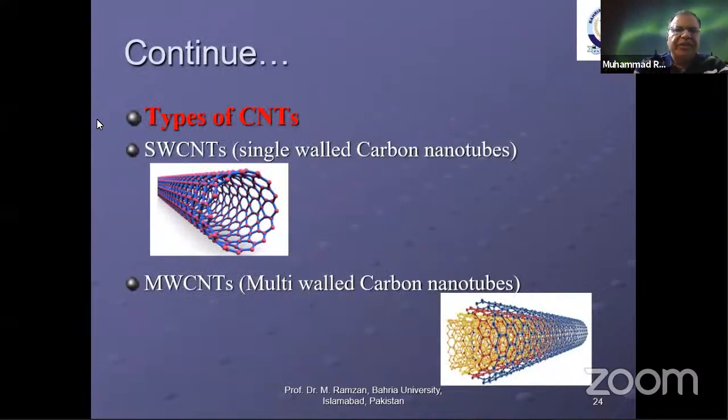Carbon nanotubes are basically of two types: single-wall carbon nanotubes and multi-wall. If we talk about single-wall, a sheet of graphene, one atom in thickness, is rolled into a tube. This creates a single-wall carbon nanotube. The method involves combining a metal catalyst with carbon-containing reaction gases, and as a result, the carbon nanotubes are formed on the catalyst surface. If the sheet is rolled once, we have the single-wall carbon nanotube, and if different sheets are rolled and overlap, then we have the multi-wall.